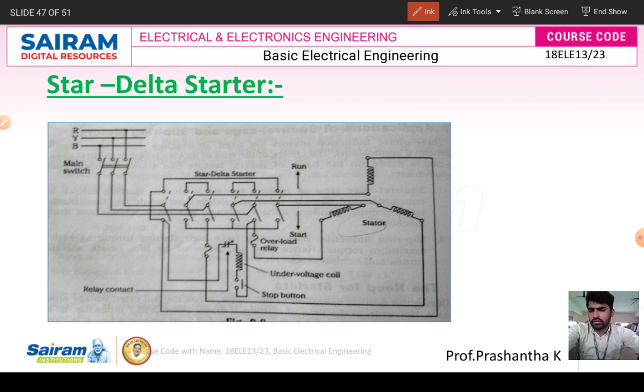The relay is like a sensor, a current sensor, okay. There is a CT present, current transformer we are using, because that current transformer sends a signal to the relay contact, so the circuit breaker contact will open. So likewise we are having, okay. And also for overloading, automatically that star to delta starter MC will trip off. Underloading, overloading will occur. It's like a normal operation, okay. That's why we are using star to delta starter.